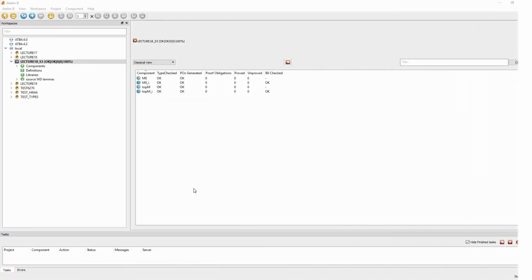Code generation may be performed at either component level. In this case, the components are selected one by one and then translated using the translation profile defined, or either at project level, all the implementations are translated. The component selected is a top-level component, and initialization of all components is performed at this level. Optionally, a makefile may be generated to automate the compilation. In this example, we are going to see how to generate code at component level and at project level.